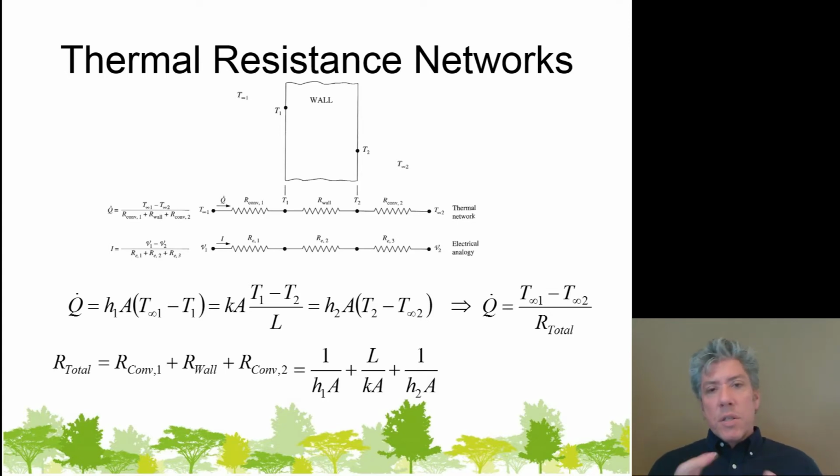Now that doesn't change the heat flow rate from the outdoor wall to the air unless all of it can change. And the way this works, the higher convective heat transfer coefficient will tend to pull thermal energy from the wall quicker, and so the temperature of the outdoor wall will drop, and that will reduce that driving force for heat transfer and thereby reduce the heat transfer rate, so that the heat transfer rate again through the entire circuit is the same.